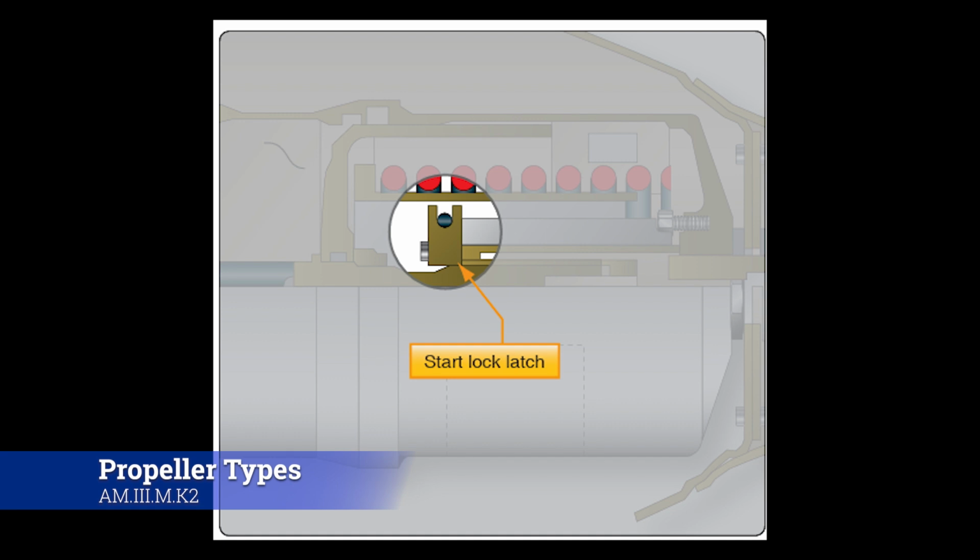Now, latches are needed to prevent excess load on the engine at startup. If the blade were in the feathered position during engine start, the engine would be placed under an undue load during the time when the engine is already subject to wear. So, long story short, there are latches in there that will allow the prop to feather and will keep it from moving into the wrong scenario. However, the latches are prevented from latching as long as centrifugal force is applied.